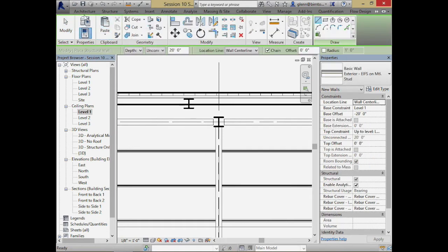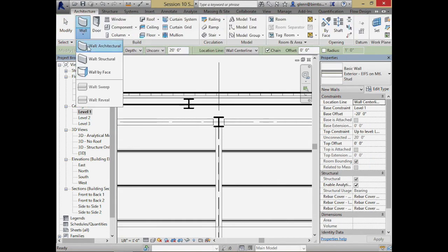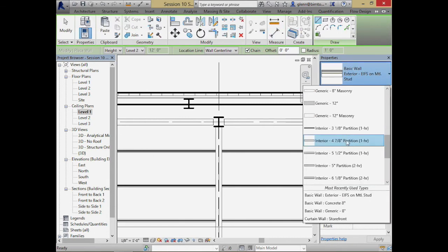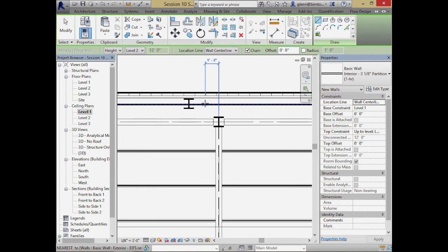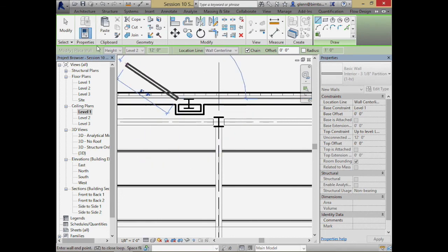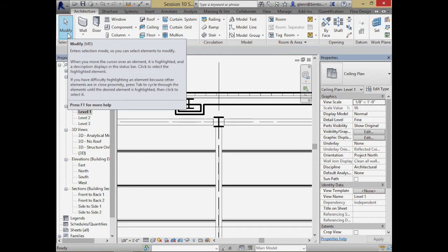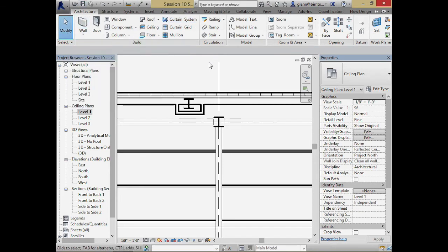What you'll do is go through and put in something that looks like this. We put some sort of interior partition in there. You'll get something that looks like this, where it just boxes in around the column. That provides some fireproofing for the column, because we need to protect it from fires that might weaken it. And when you see things like that, that's something we call a pilaster. So it's just a column that's embedded in a wall.